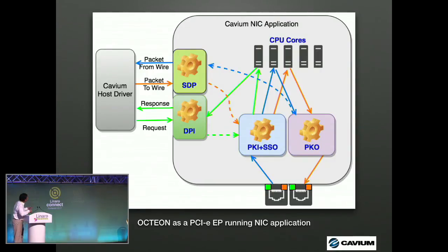So all three lines can be used for both control plane and data plane, so you're limited only by the PCI bus bandwidth. The format of the message dictates how much hardware processing is done. For the orange and the blue lines, you are deliberately going through a block that will treat it as a network packet. For the green, it's an opaque packet, so you skip the hardware packet processing.